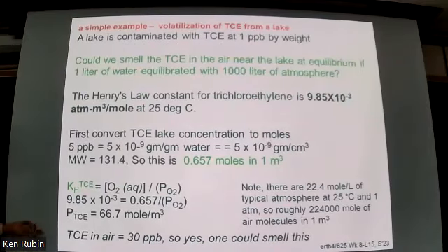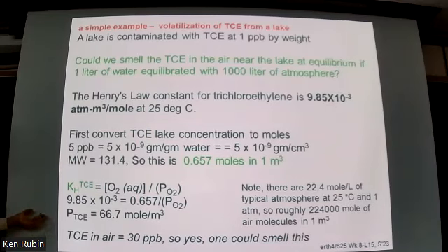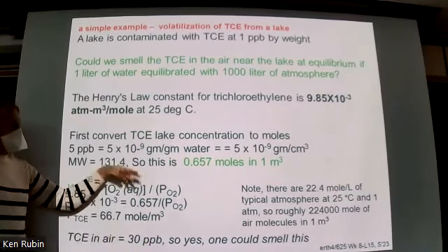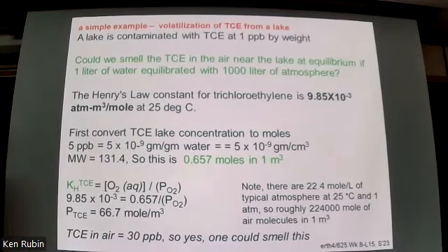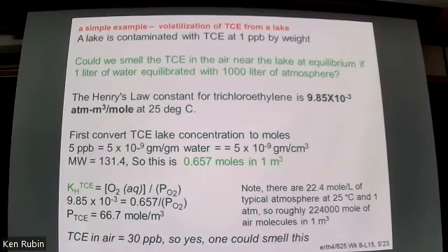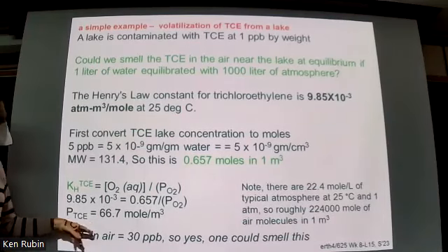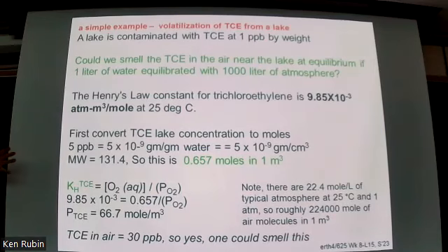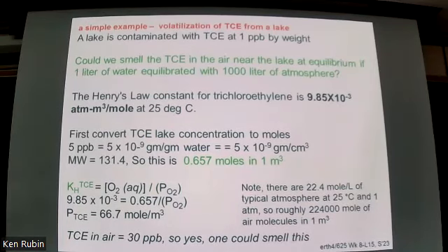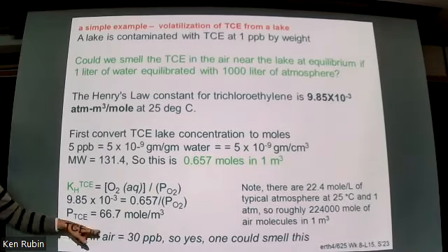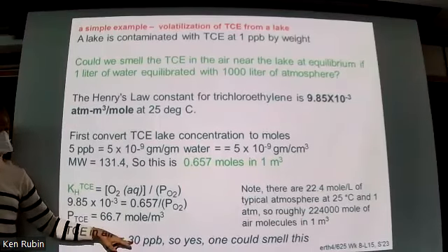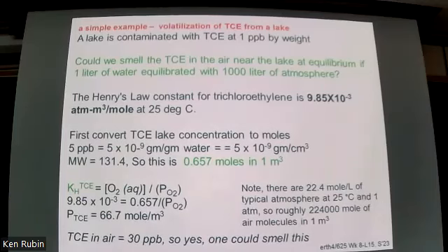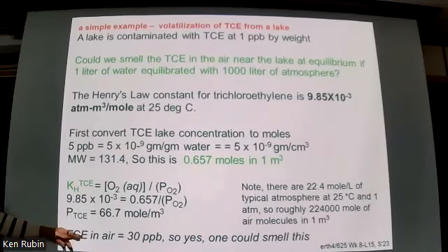And so when I do that, you find that the TCE in the air equals 30 parts per billion in this example, if we are looking at a volume that is basically 1,000 times as big as the volume of water. That's a sort of realistic value, which is something you would definitely be able to smell, right? It's higher than the odor detection limit of 20. Not toxic, since it's below the toxic threshold, but you would smell it.